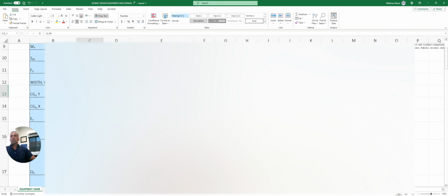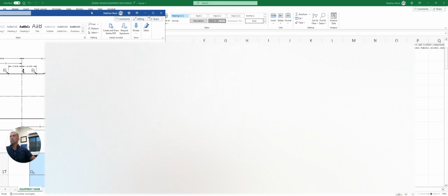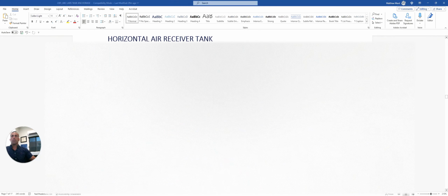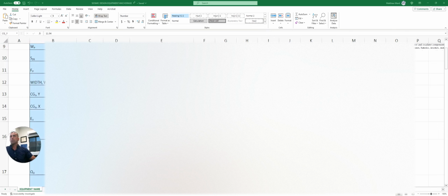And then the vertical dimension to the center of gravity. Now, the picture doesn't necessarily tell me exactly where it's at, but obviously it's going to be somewhere about 25 inches. So I'm just going to put in 25. If I wanted to be safe, maybe I'd put in 26 or 27. But we'll see that there'll be a large factor of safety even with 25 in here.